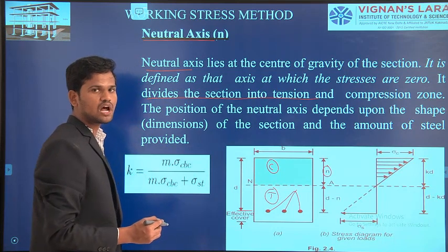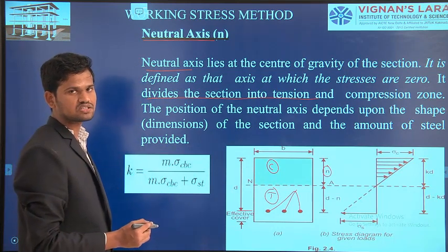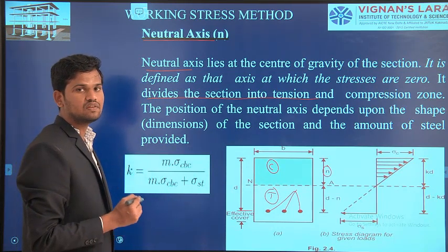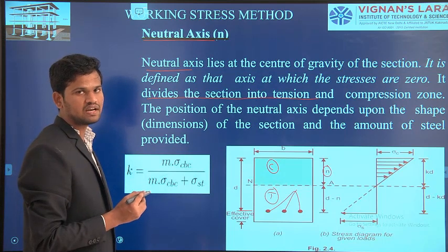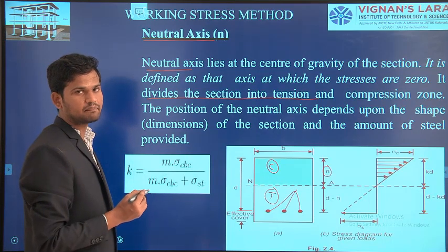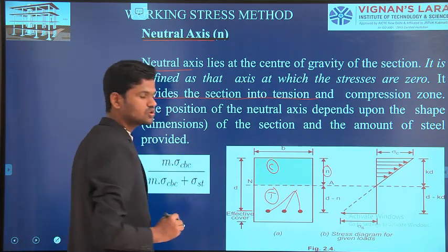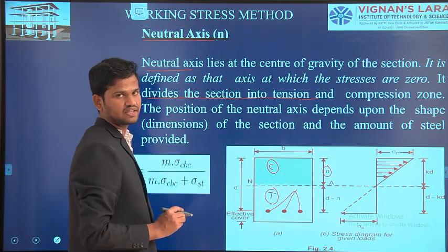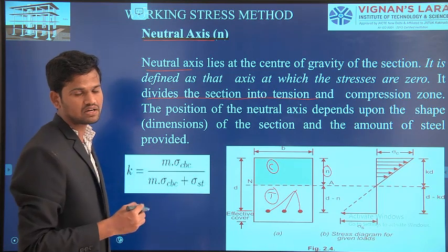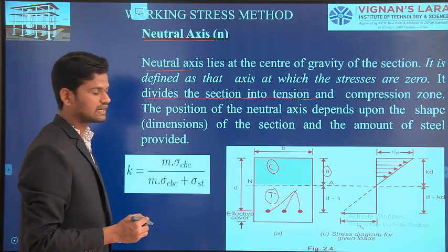After effective depth also we are providing concrete. Why? Because if you are not providing the concrete below the tension zone, the steel will get exposed to the environment and corrosion of the steel may happen, and the structure will collapse. Hence after effective depth also we are providing concrete. That effective clear cover we will discuss in later classes.